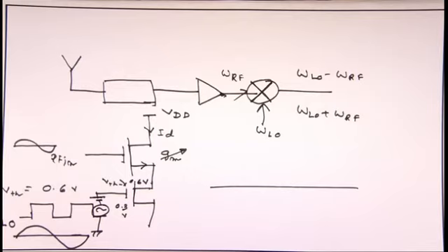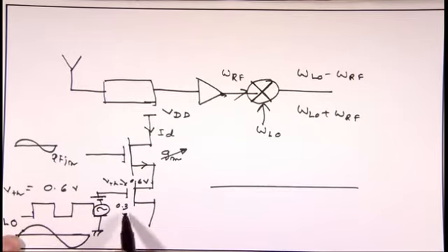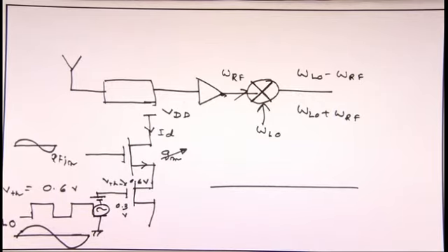So, if the voltage is above, say, 300 millivolt, that is 0.3 plus this 0.3 already biased, then it will cross the threshold and the transistor will be on, and in the negative swing the transistor will be off, clear. So, it will act just like a switch.